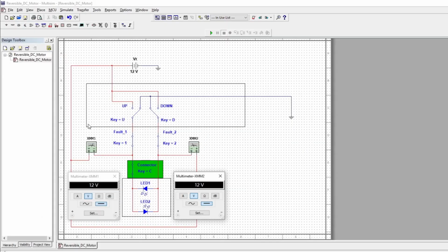Okay, so to just get you orientated here, here is the driver's side switch assembly right here. And you've got the 2 single pole double throw switches. So they don't move in tandem. So when you're pressing up, right, this switch moves. If you're pressing the down or forward and reverse, depending on if you're dealing with a power seat horizontal motor, they move separately. So you see here I have some faults put in on either lines coming out of the